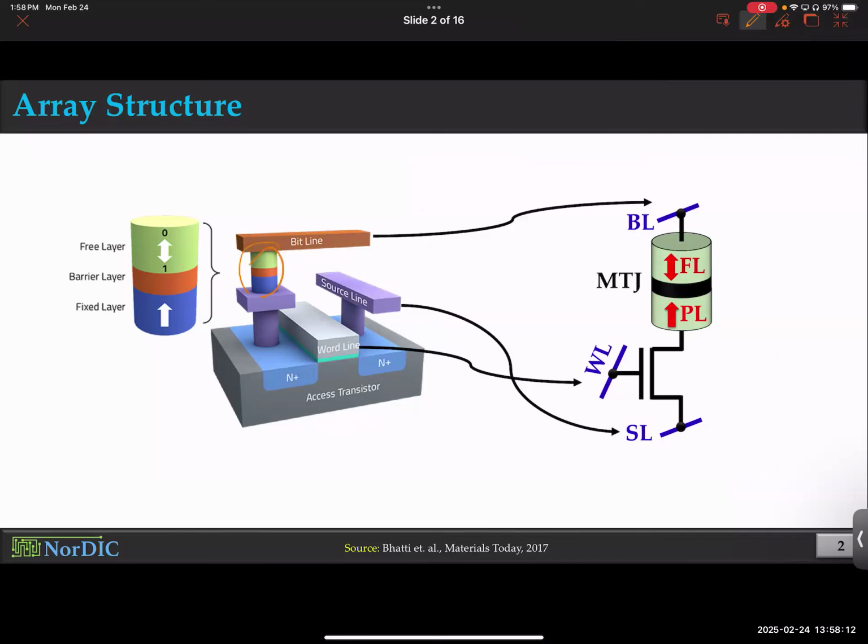this magnetic tunnel junction can be fabricated on an upper layer, back end of the line. That means there are two things. First of all, in back end of the line, you can be very creative. You can make all of these underlying things in a conventional foundry, and you can have a specialized foundry that only makes the top layer. Does that make sense? Just imagine making a cake. Somebody bakes the cake and does everything else. All you do is just put a cherry on top. So you are a cherry factory. All the bakers send you the cake and you just put a cherry on top. So basically, that's exactly what you could do with MTJ. You could fabricate everything else, and you are just putting in the magnetic tunnel junction in a separate facility.